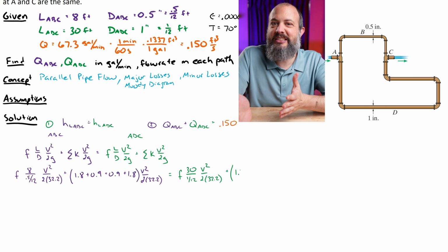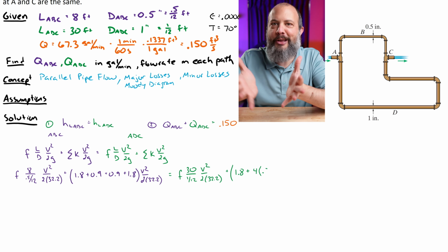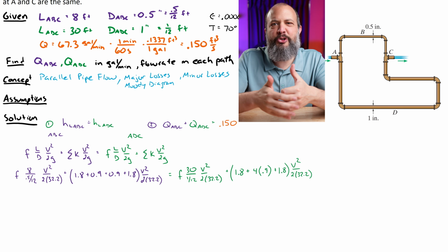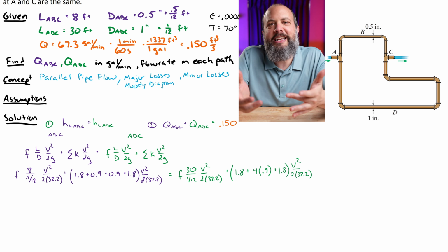Right, so we can plug in similar numbers over on the green side where they also go through two T-joints, again, at the 90-degree angle of the T-joint, so that's the value 1.8. And there's 4 regular 90-degree corners, so 4 times 0.9. Because again, I'm assuming that those are threaded rods also.